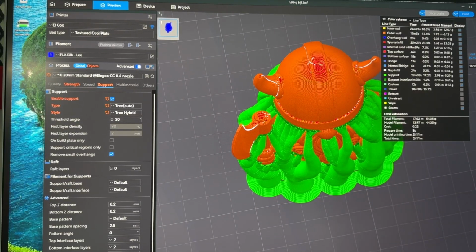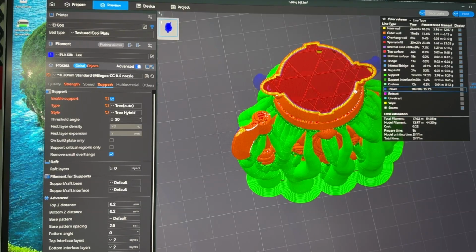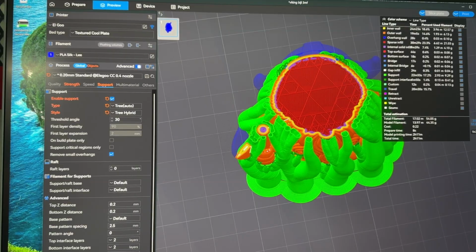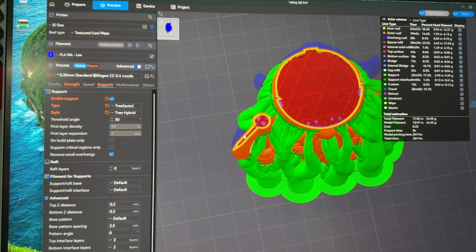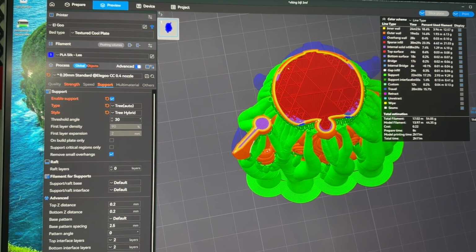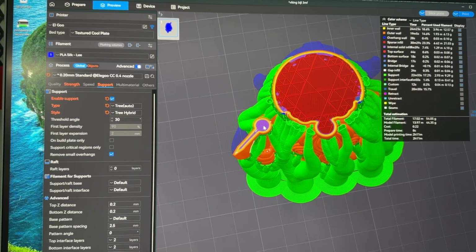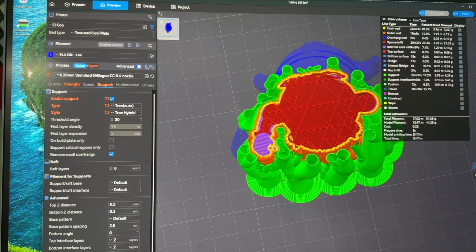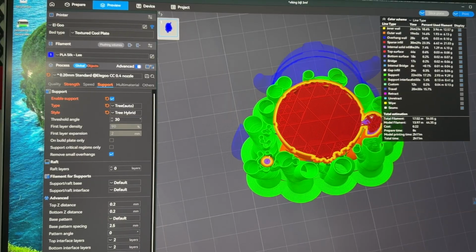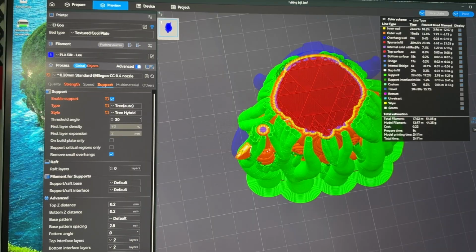If I go down through here and pull my slider down, you see the infill in here, the pattern. Okay, this is support cubic. So it puts where it needs support, it puts a little heavier than it does where it doesn't. But if you look here in the axe, we've got support cubic going on. If we keep going down, it goes to that one right there. Look at that. That's 100% infill. And so now the handle is 100% infill, and even the hand there where I have that cylinder is 100% infill through that whole feature.